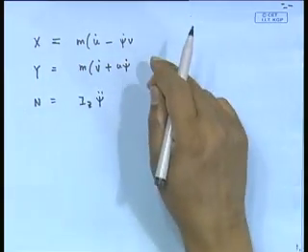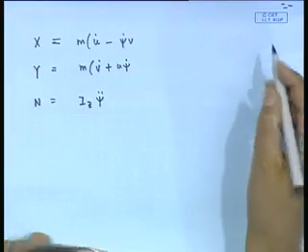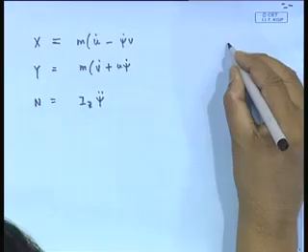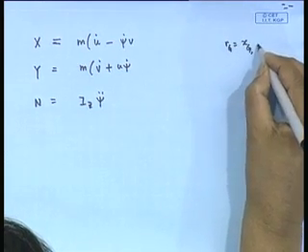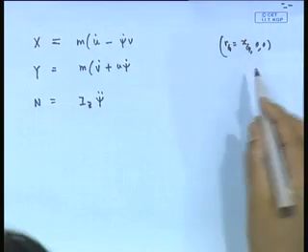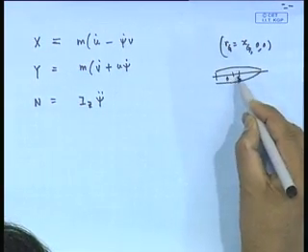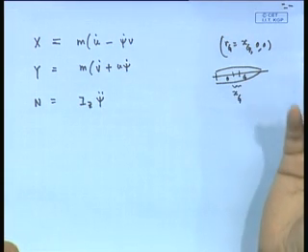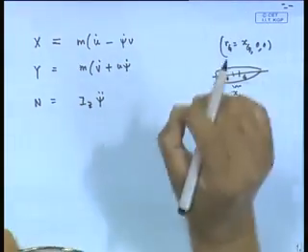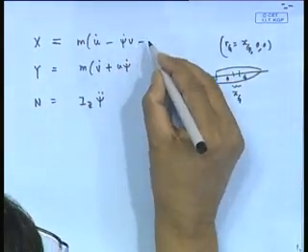This was of course the equation if I had the origin at the center of gravity. But if my origin was located at some other distance, and typically I would take r_g to be (x_g, 0, 0), because normally you would always choose the body coordinate at a distance x_g. Normally the center of gravity is on the center line and the origin also you will put on the center line, just x will be different. So, if I just took non-zero x, then the extra terms that come out are